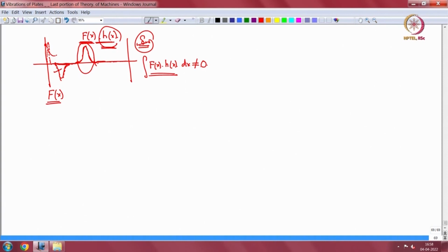So that is a sketchy proof of the lemma of calculus of variations, and that is how you show that the differential equation independently is 0, and then you get boundary terms. You get a boundary term with delta W, and then you get a plus or a minus boundary term with a delta W dash.